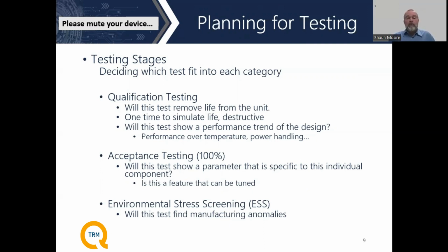The first thing we do is go into qualification testing. Qualification testing has us measure the unit performing over essentially all of its environments, and try to simulate that the part will survive over its full life. So what do we do here? We will take data over temperature to verify the thermal characteristics.